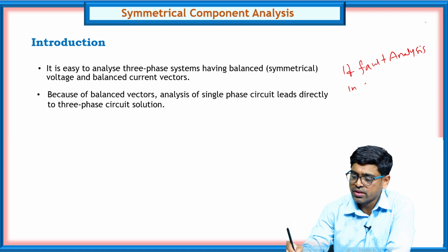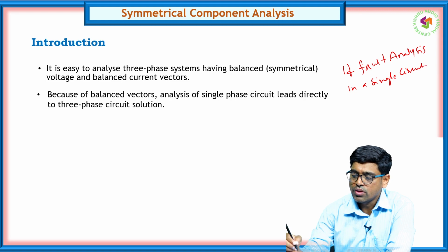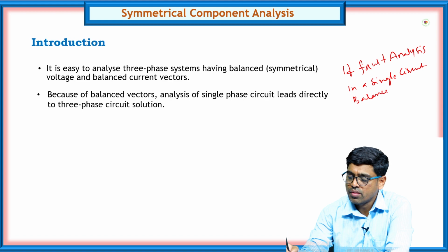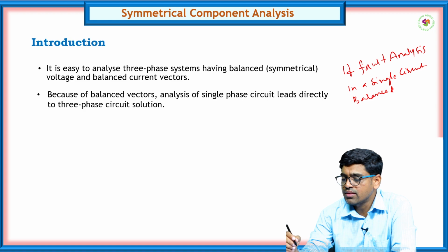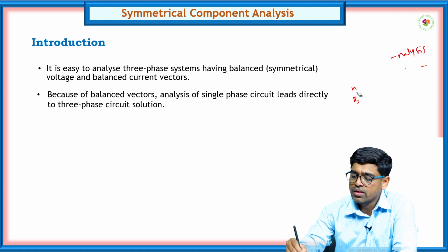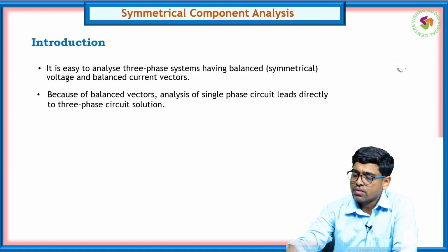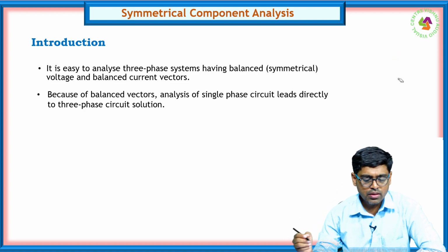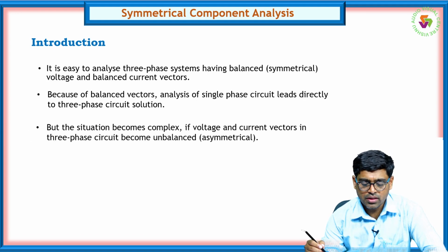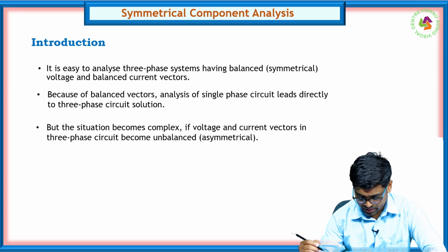in a single circuit. So fault analysis in a single circuit is possible if it is balanced. The time to calculate this analysis is very short. If the system is balanced, we can easily calculate whatever fault analysis it is. Because of balanced vectors, the analysis of a single phase circuit leads directly to a three-phase circuit solution, but the situation becomes complex if the voltage and current vectors in the three-phase circuit become unbalanced.